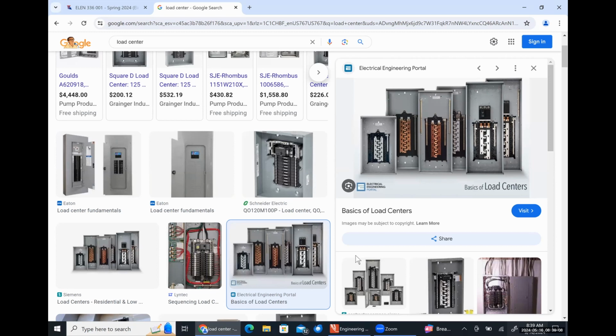And on one side, they're effectively on the positive 120 side, and on the other side, they're the negative 120 side. And actually, that's not true. It's going to go positive 120, negative 120, up and down. It's kind of like a laddered structure based on those little tabs. And so if you ever see a breaker that actually takes up two spaces, that's for a 240 volt circuit.